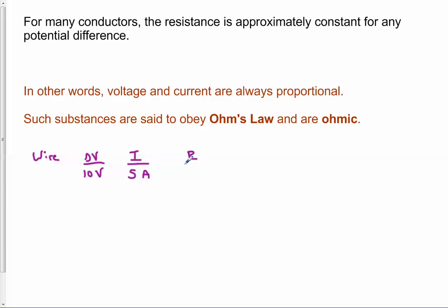And so that meant that the resistance was 10 volts divided by 5 amps, so 2 volts per amp. I'll use the unit now, I'll call it 2 ohms, right? That was a resistance of 2 ohms. Now, let's say we have control over the delta V. We can choose what delta V to apply to the two ends of the wire.